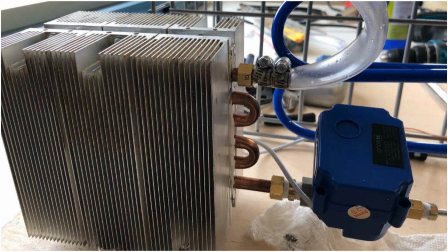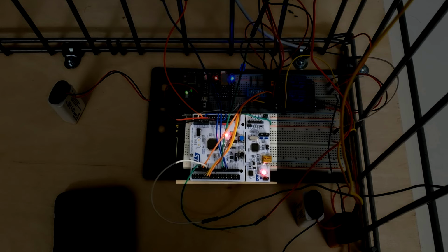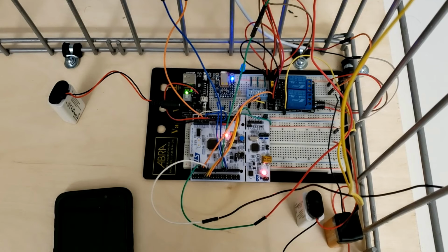This completes the cycle, which is regulated by a ball valve. This ensures that a temperature difference is present for the expansion to occur again. The ball valve at the bottom of the structure is controlled by a 2-stage float switch located inside the reservoir by an STM32 microcontroller. We can communicate with the system using the UART Bluetooth module and a mobile device.